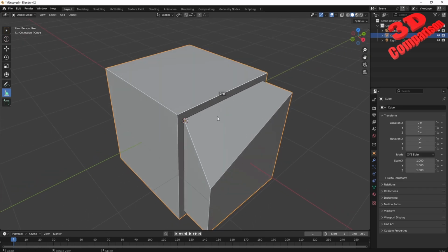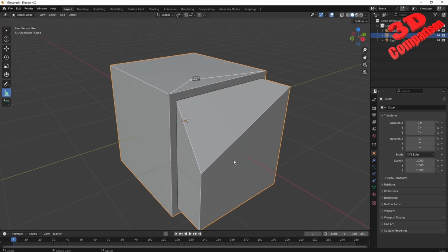If you want to do an angle measure, we can also just move the mouse over here on an existing dimension. We can hold down the left click, and then we can decide where to position that additional vertex that will give us the angle. If you want to measure an existing angle like this, if you're just gonna start a new measurement, you will have to position those points.